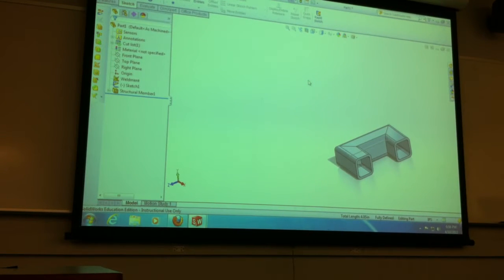You're not so much calculating the stresses, but what are the 4 variables in the beam? Deflection, slope, shear force, bending moments. So you're only calculating those 4. You don't care about the stress analysis so much here, as you're treating these as beam elements. Okay? So the whole process of solving is different. You're not doing a regular stress analysis.